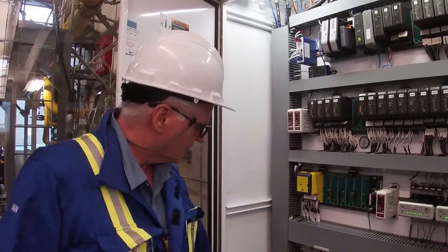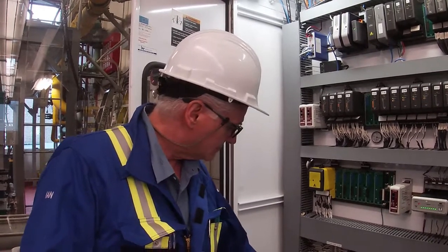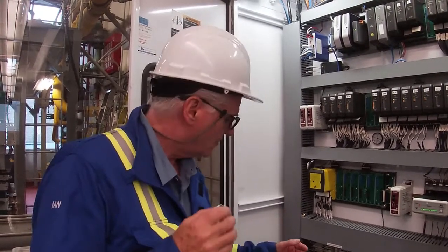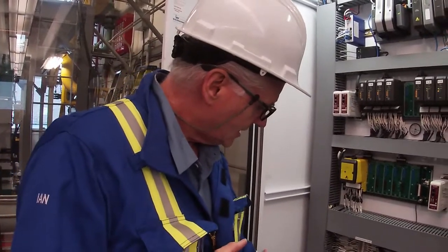And so we had to put the relay in between. So when it does its testing to look at the integrity of the loop, there's not enough current to pull in the relay contact. So that's why we put the relays in here. So on the outputs, we actually have 6 relays, and that's the reason we put those relays in there.